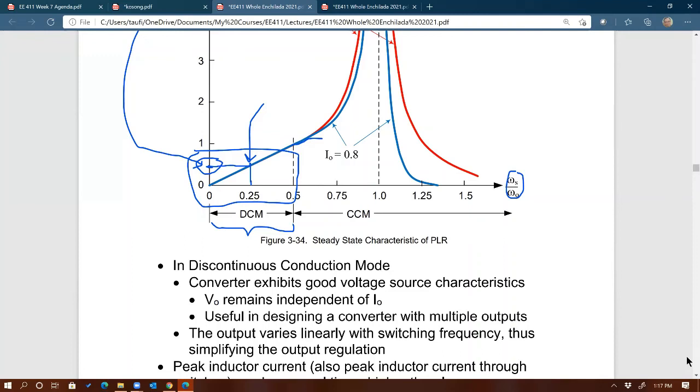That's correct. Yes, because harmonics are just high frequency components that you should be able to filter out to a certain extent. So you block the harmonics at the input with input filters, and you also block the harmonics at the output by putting a harmonic filter on the output. Low pass filter, basically, right?